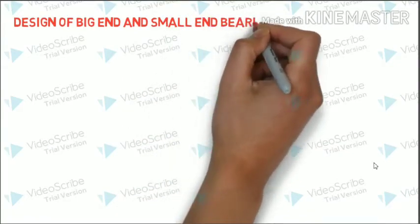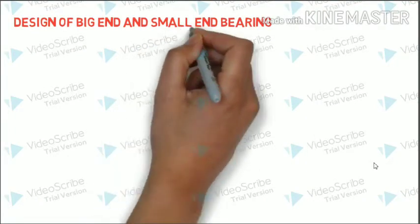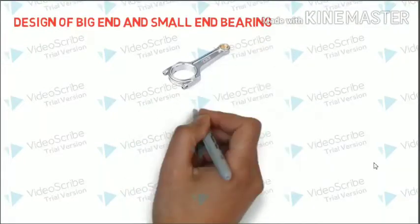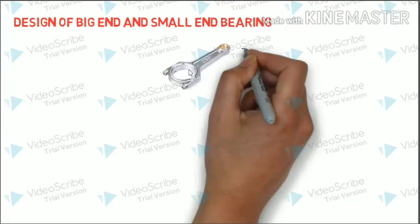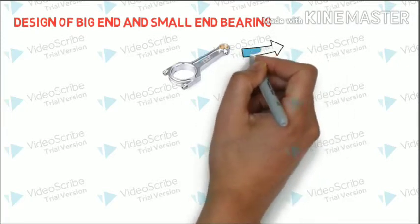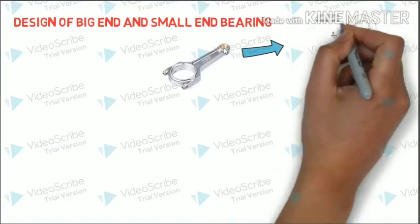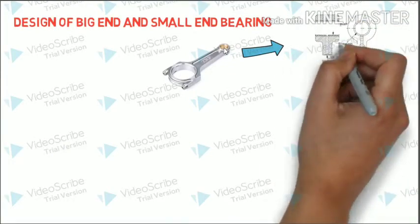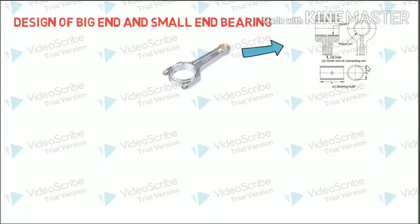Now let us move on to the design of the big end and the small end bearing. Here all you have to do is find the dimensions of the big end and the small end bearing. These bearings are something that is kept inside the big end and small end, so it is effectively a simple hollow cylindrical section. Let us enlarge this view. Your small end will look something like this, as you can see from the figure. This is the bearing bush.